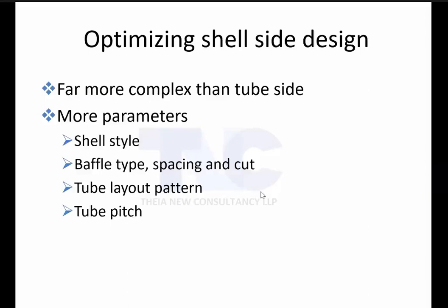So again, as I said, what are the things that you should consider? The tube pitch, tube layout pattern, spacing and cut, shell style. What is the shell style? As I said, the TEMA classifications. So remember all these things, whatever I said: where to use E shell, where to use J shell, where to use A, where to use B, where to use W, where to use S, where to use T. Whatever I said, make a note of it.